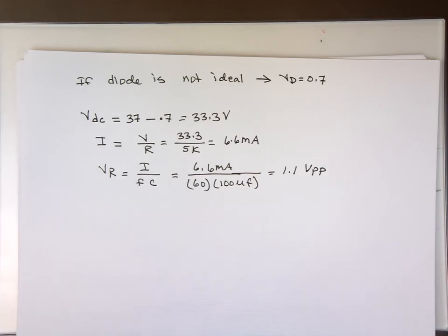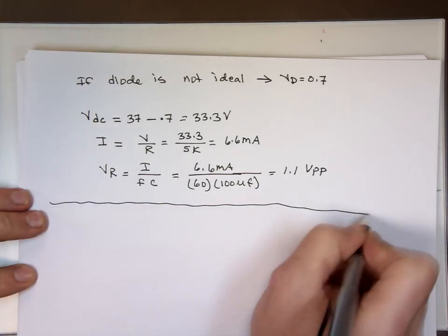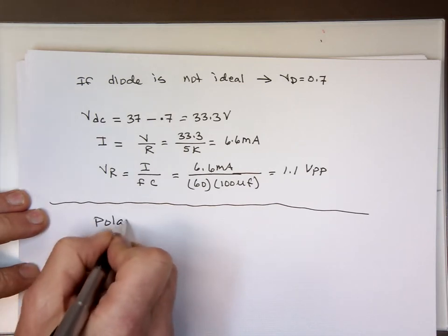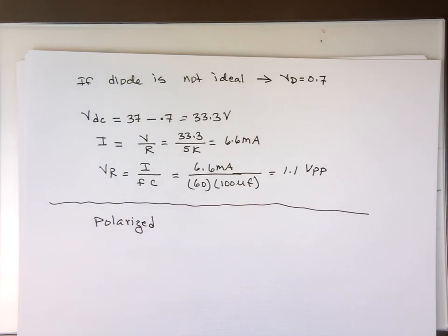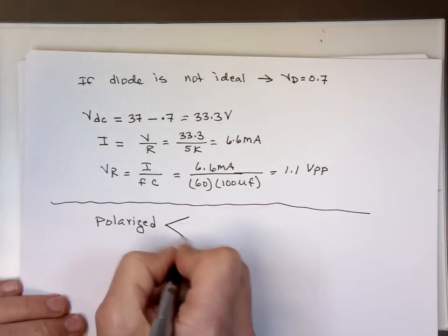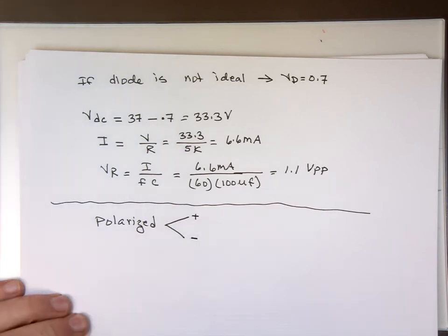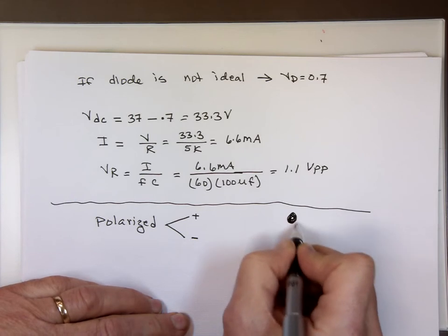The one thing I will remind you, if you were to build this in the lab or troubleshoot it, when you grab your capacitor, take a look at it. Some capacitors are polarized. What does that mean, polarized? When you look at them, they have a positive and negative end. So your capacitor in the lab looks something like this, a little blob with two wires coming out of it.